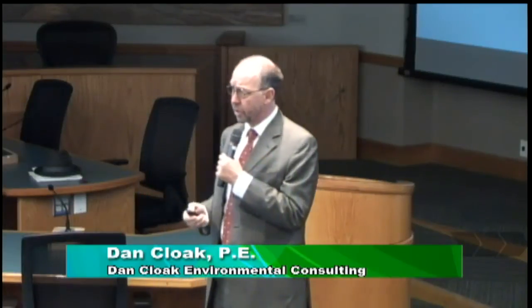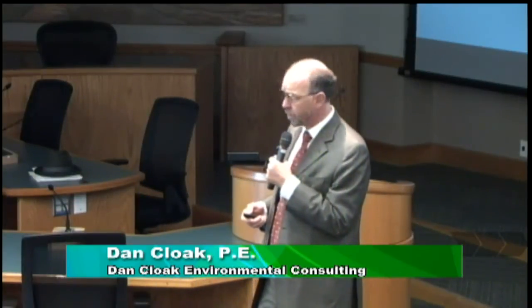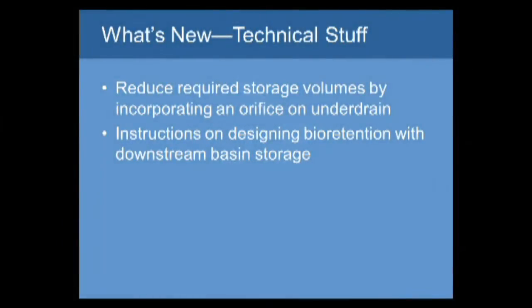The technical stuff that's new are really two things. One is we've found a way to reduce the storage volume, the amount of gravel that's required beneath the underdrain on bioretention facilities. This is done by incorporating an orifice on the underdrain, which, during peak events, events which are on the large end of the spectrum of storms that we need to control, will allow runoff